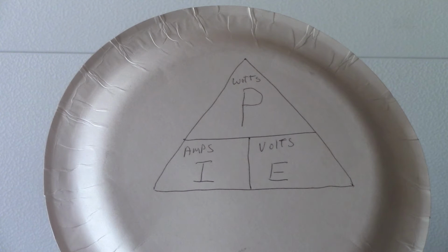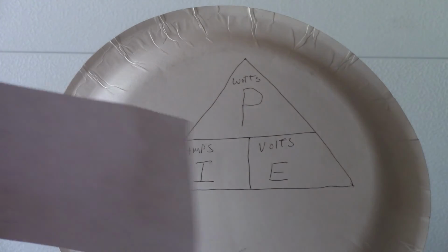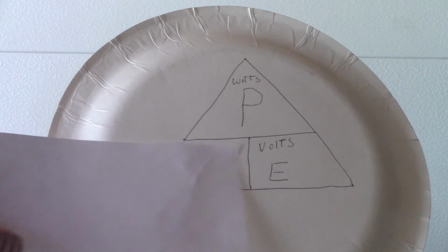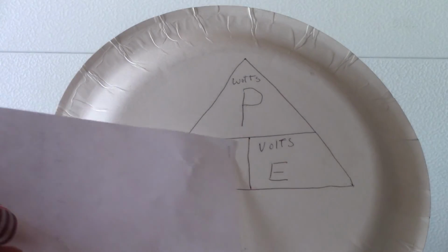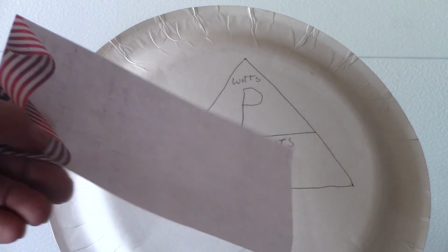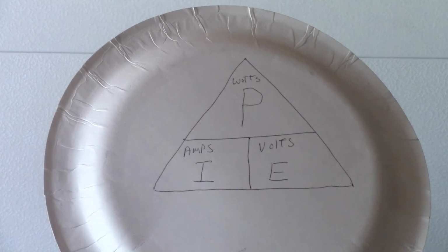But you can see where people get in trouble. You're running a half an amp on the other side of the inverter, but on the DC side of the inverter, you're running 5 amps, 10 times more. And this is where people get in trouble sometimes. Think of that. If you're running 120 watts on a 120 volt circuit, that's 1 amp. But if you're running 120 watts on a 12 volt circuit, that's 10 amps. So you see what I'm talking about?